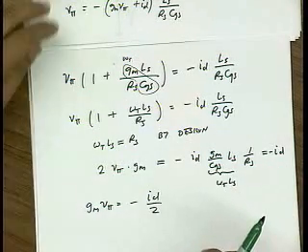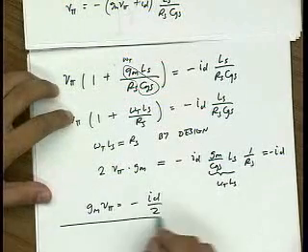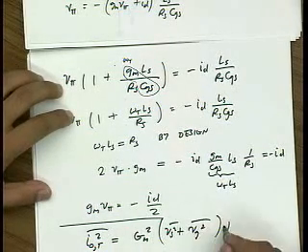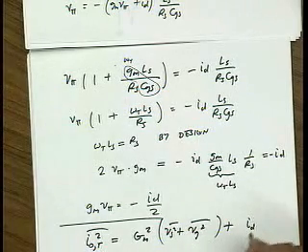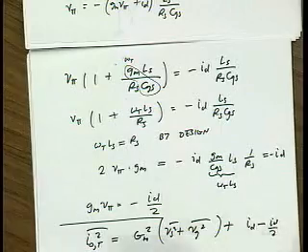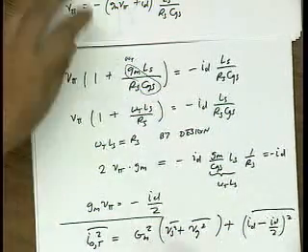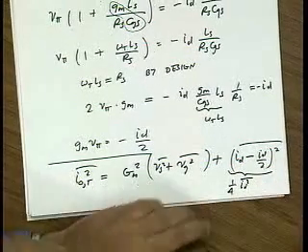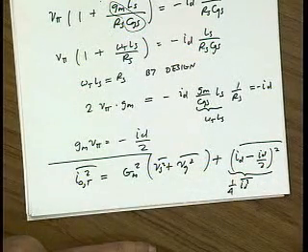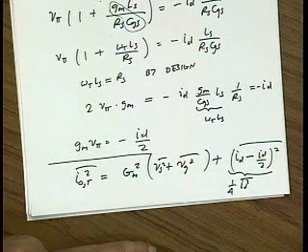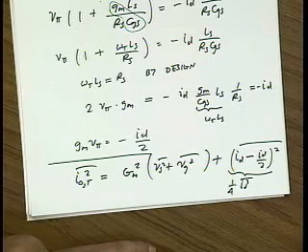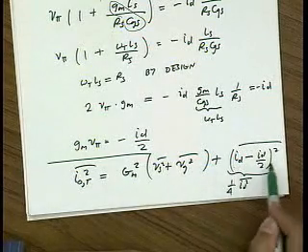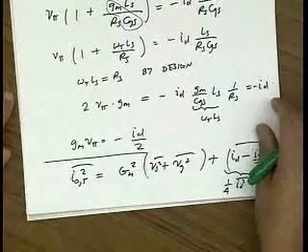Now if you think about it, I know exactly all the noise contributions. I can now say that the total noise contribution is gm squared times source noise, gate noise, plus drain noise minus drain noise over 2, right? RMS value. In other words, 1/4 of the RMS value of the drain noise ends up at the output. Questions? Remember, the important point is that this current that comes back at you is perfectly correlated with this, and so they actually cancel each other out. They don't cancel completely, but it reduces the noise contribution.